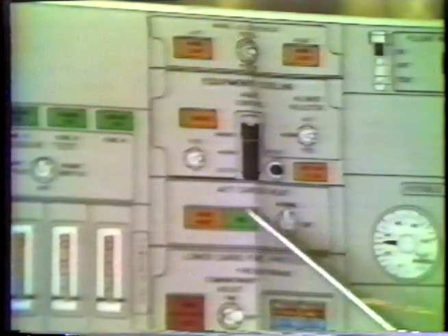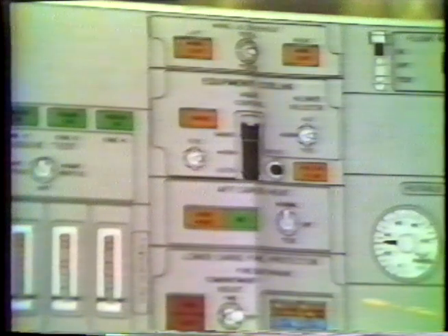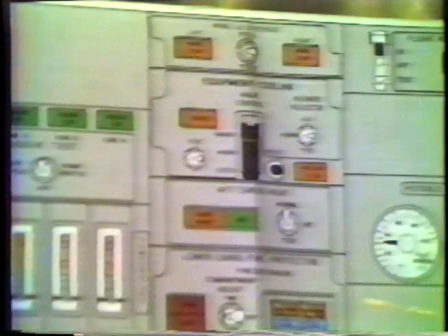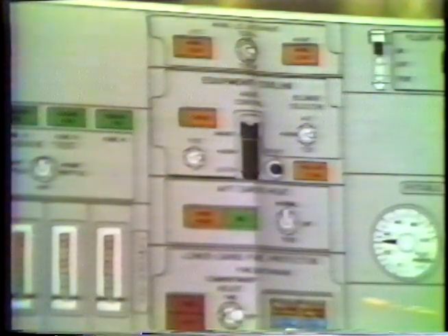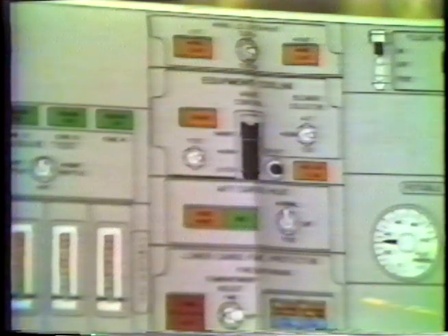Aft cargo heat. The test position overrides the normal temperature control and causes the green light to come on. And this is normally done on a cockpit setup, and it should only be held long enough to determine that the valve comes to the open position. Aft cargo heat, as mentioned before, is supplied by pneumatic air on the line between the two isolation valves. In order to do the test, you do not need pneumatic air. The light just indicates whether the valve is operating properly or not.